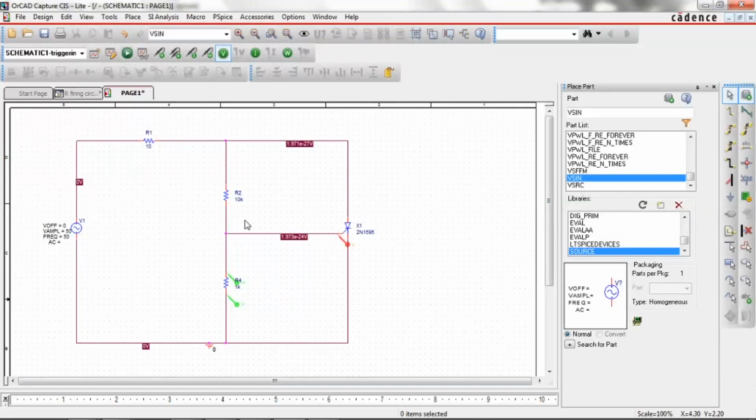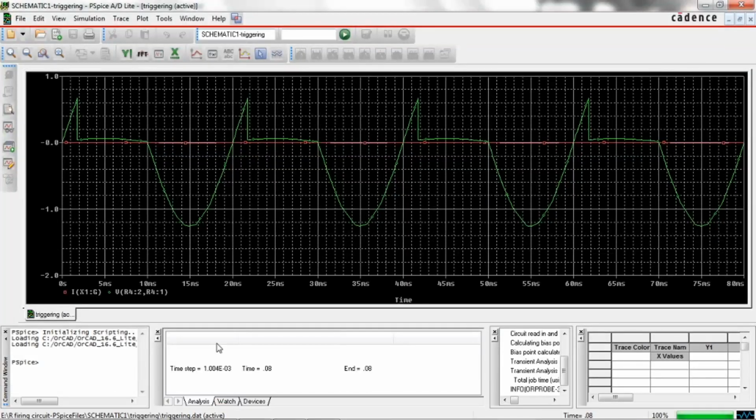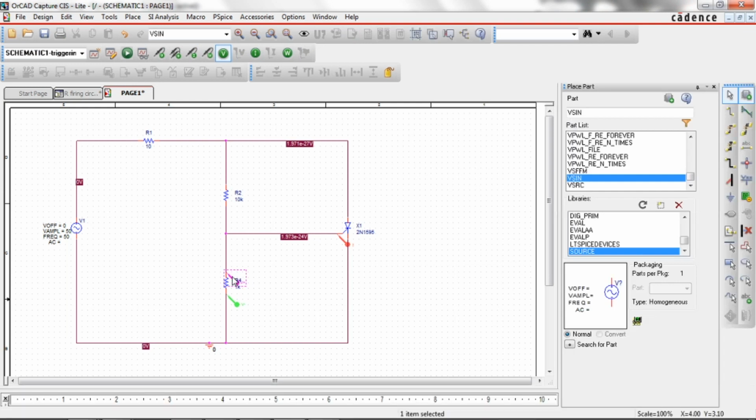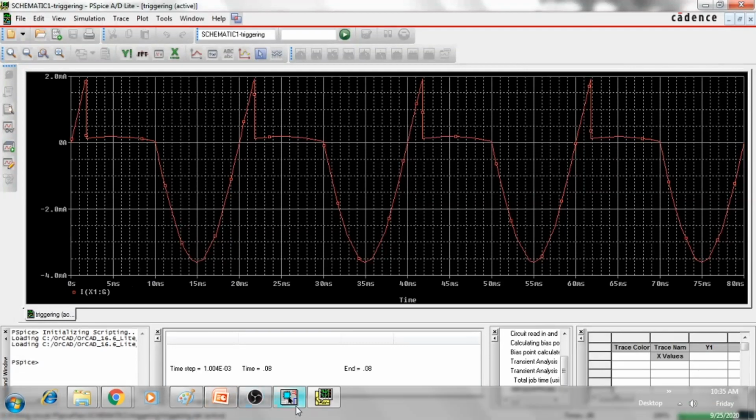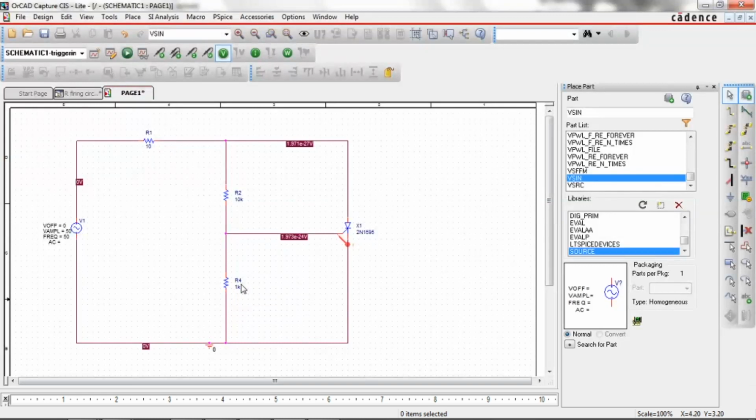See, then why this circuit? Okay, can you see the output voltage? You see here, what is the time axis? Okay, I will go to the current. See, this is the time axis, this is 0 to 10 milliseconds, it is 20 milliseconds. When exactly has the gate current reached 1.9 milliamps? Which component is responsible for the gate current? The voltage, this resistance, and these two resistances, and the voltage which is developed across this